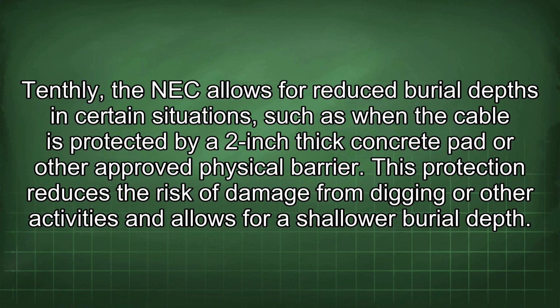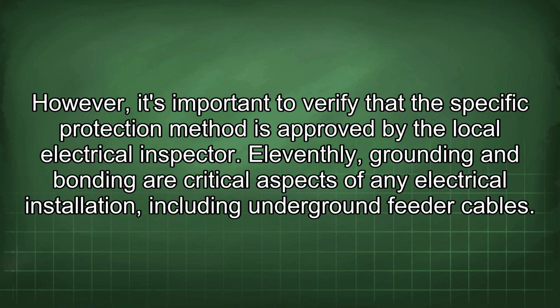Tenthly, the NEC allows for reduced burial depths in certain situations, such as when the cable is protected by a 2-inch thick concrete pad or other approved physical barrier. This protection reduces the risk of damage from digging or other activities and allows for a shallow burial depth. However, it's important to verify that the specific protection method is approved by the local electrical inspector.